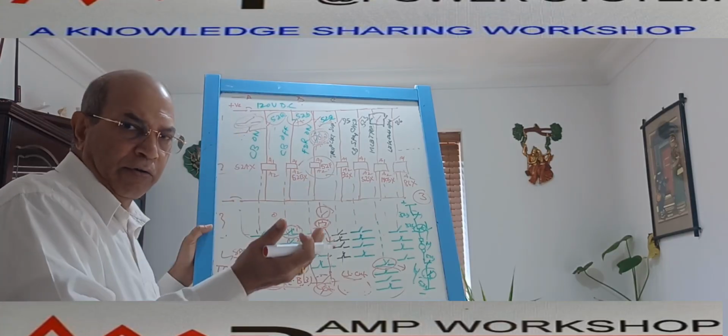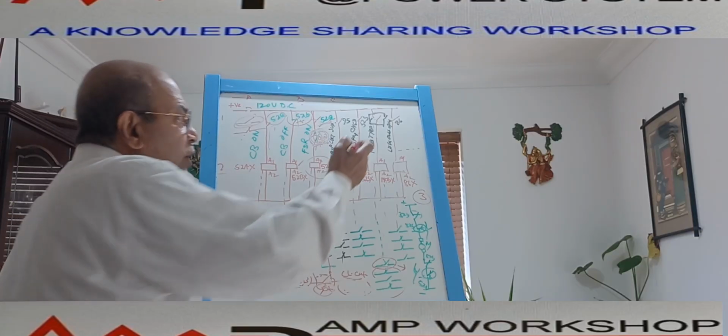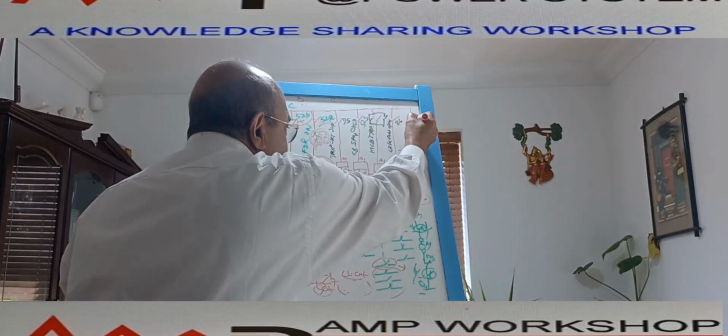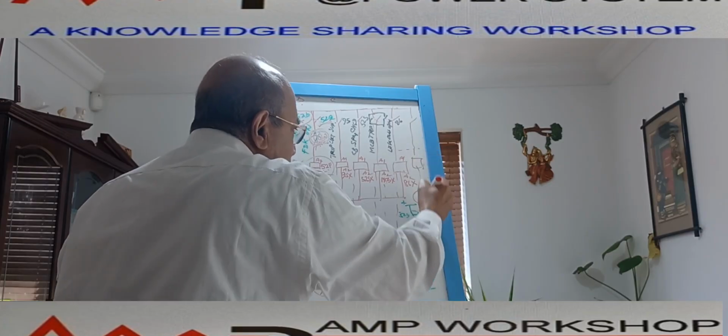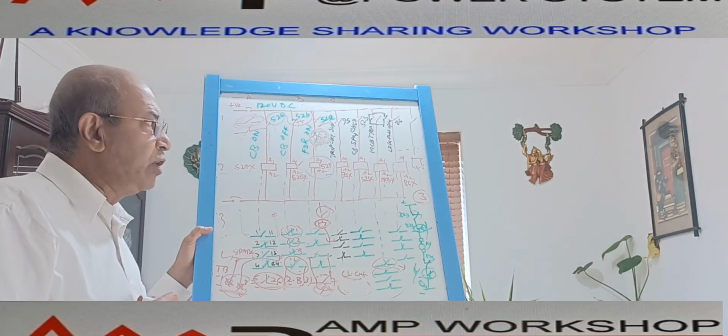Suppose for the breaker failure relay, breaker failure has taken place and it has only limited contacts. Then we can use one of the breaker failure contacts over here as the master contact, then we use an auxiliary relay, and that relay's output contacts will be used wherever we need them.